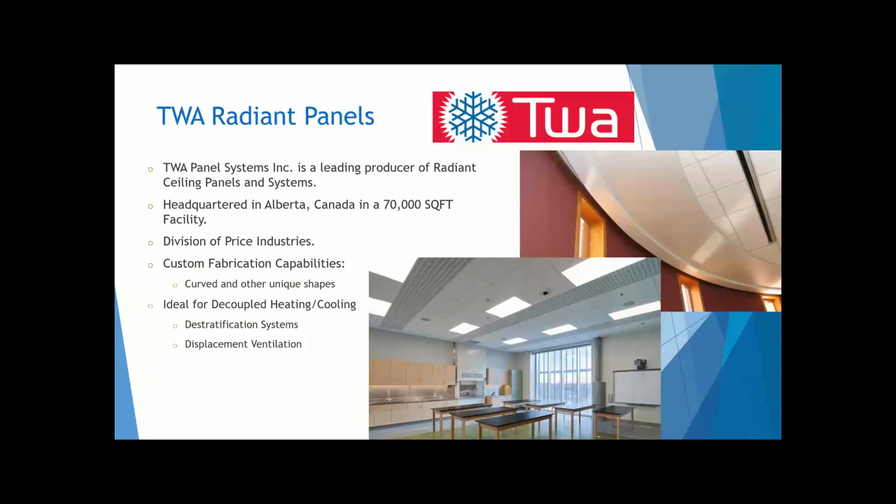On the other hand, a great transition here is that we actually use these for most of our displacement ventilation products, displacement ventilation systems. And we'll talk about that in a second, but this bottom picture here is actually an example of another displacement ventilation system in a lab room. So this is a displacement ventilation diffuser, and over here we have radiant panels throughout. You see these right here, where this is actually radiating that heat to the floor.